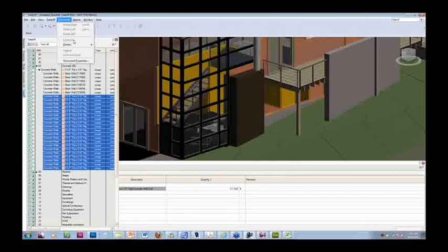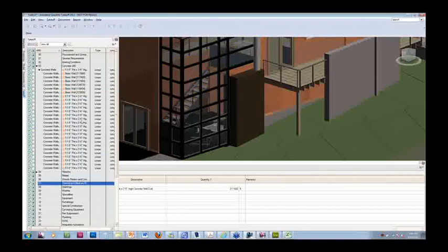So at least you will know. Even though it's not linked, and you have to remap it again, it will remember what the differences are, so you don't have to start over from scratch. And it will allow you to compare and add on to what existed. And better yet, if in the previous takeoff you didn't add a particular component that wasn't there, you can save the QTO catalog from now on and reuse it in the next takeoff. So it means that you can continue developing that database template and use it on the next calculation or even on the next project.